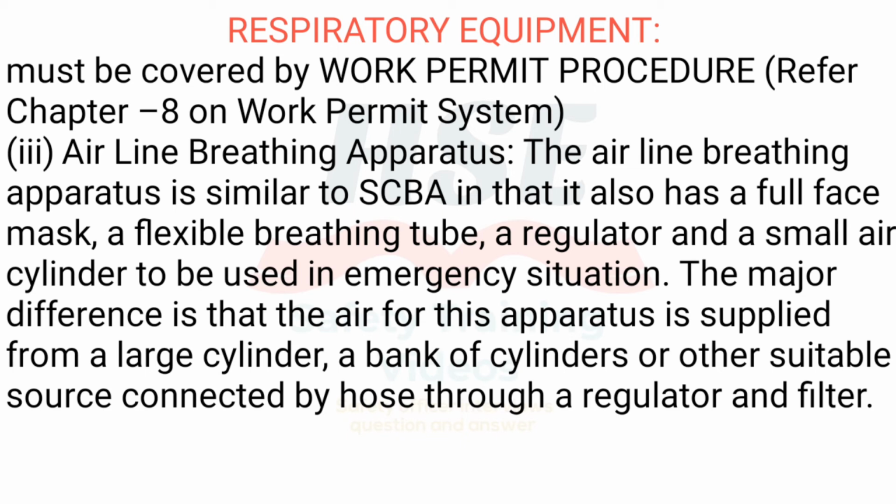3. Airline breathing apparatus. The airline breathing apparatus is similar to SCBA in that it also has a full face mask, a flexible breathing tube, a regulator and a small air cylinder to be used in emergency situation. The major difference is that the air for this apparatus is supplied from a large cylinder, a bank of cylinders or other suitable source connected by hose through a regulator and filter.